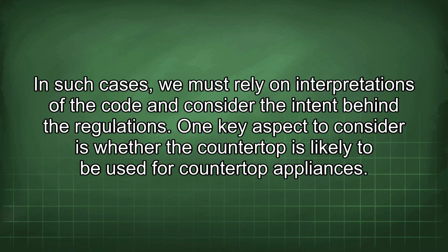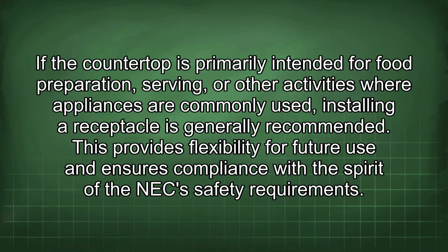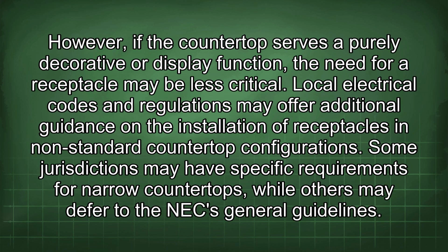One key aspect to consider is whether the countertop is likely to be used for countertop appliances. If the countertop is primarily intended for food preparation, serving, or other activities where appliances are commonly used, installing a receptacle is generally recommended. This provides flexibility for future use and ensures compliance with the spirit of the NEC safety requirements. However, if the countertop serves a purely decorative or display function, the need for a receptacle may be less critical.